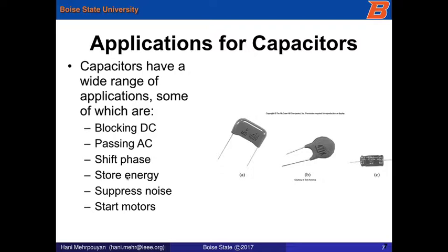They can be used to store energy, and for example, in renewable energy sources, there are discussions of, or even prototypes of, very large capacitors that can be used to store energy. They can be used to suppress noise, mainly DC noise probably. And they can also be used to start motors. So for example, a lot of the air conditioning compressors that are sitting outside the homes are equipped with a large capacitor that is used to start the motor at the point of starting. And so a lot of times when the compressor doesn't work, it's actually the capacitor that has failed, and it's an easy, very cheap fix.